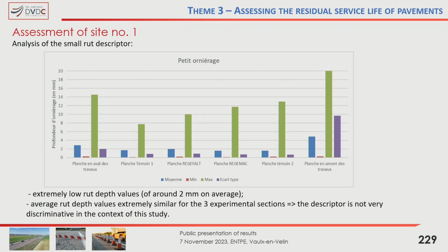Once we knew that we'd put them all in the right order, as I said earlier, in terms of the surface information, we summarized it for each document that we had, so for each portion of the road pavement. Here, you've got the information for one of the portions, and what you need to look at in particular is not necessarily the minimums and the maximums. You should look at the averages, because sometimes you can have slight drifts in terms of the measurements.